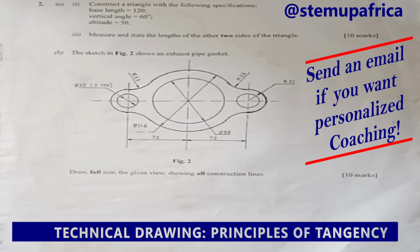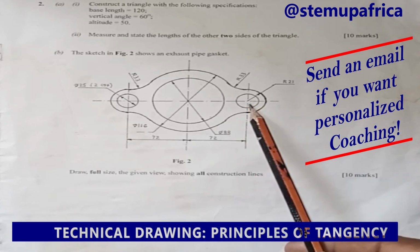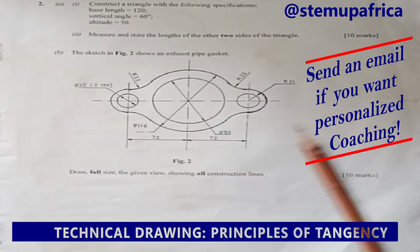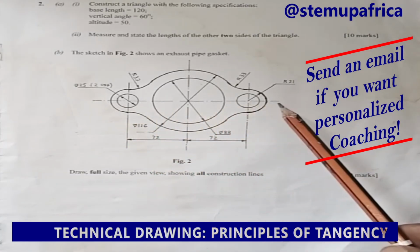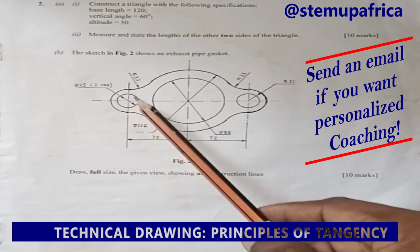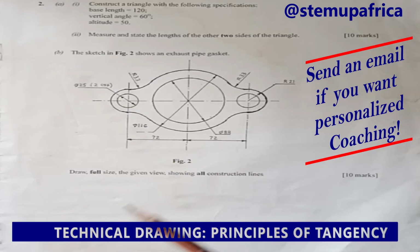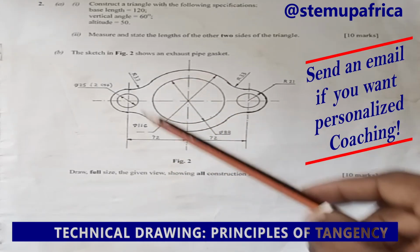So if you look at the figure, we are told that the distance between the two centers, from this small circle to this small circle, is 72. So to start this drawing, we start by drawing this horizontal line. We can mark out 72 to the right and 72 to the left in order to draw these two circles. At the same time, at the midpoint of that 72, we can draw this circle and this circle.